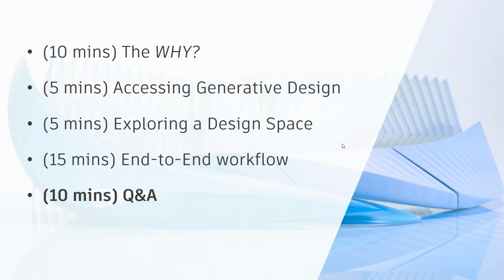Yeah, this is a good point, because this is also something that I would like to clarify. The interoperability between Inventor and Fusion 360 works in the way that I can open an Inventor native file in Fusion 360, and if I update the Inventor file in Inventor, I get the update in Fusion 360. Or I can open a Fusion 360 native file in Inventor, and if I modify the Fusion 360 file in Fusion 360, I get the update in Inventor. So that's the way it works.